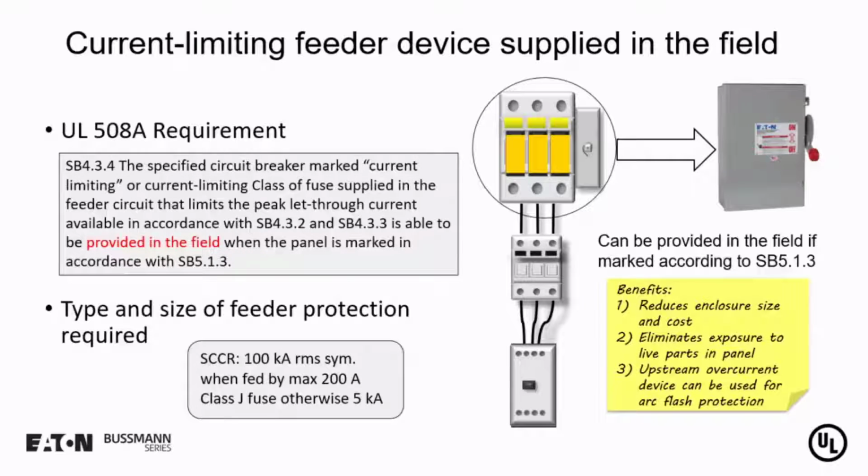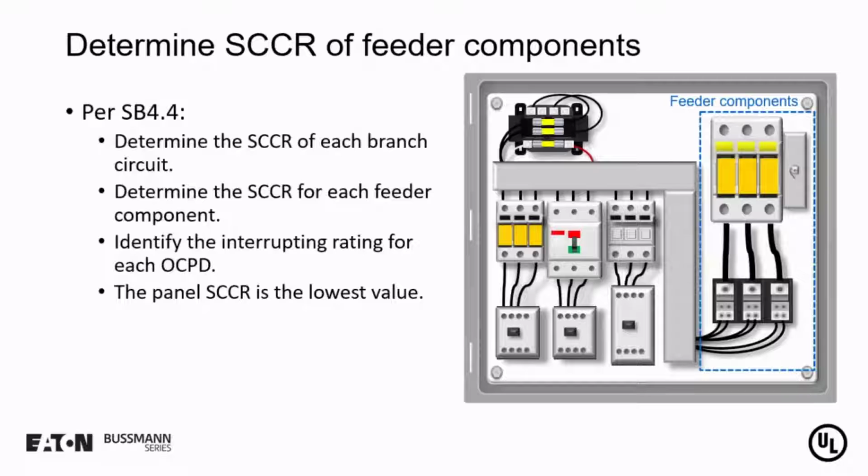And you also will have the case where when I turn that disconnect off outside of the industrial control panel, everything in there is de-energized. That helps improve electrical safety. And with that, I'll turn it back over to John to discuss how we address the feeder circuit components.